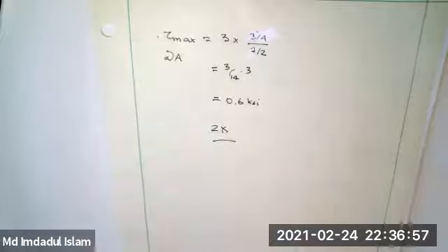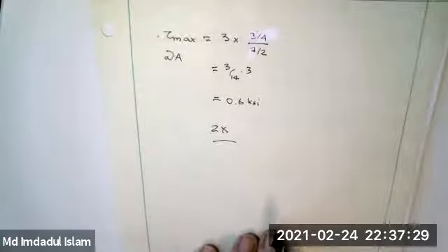So what I'm trying to tell you is the books give a lot of attention to the shear stress due to the shear force. Okay? There's quite a bit written in books about it. And it's all correct, at least as far as I can tell. The thing is that those stresses, first of all, they're at a different location. I've seen practicing engineers occasionally try to add the two. That's wrong. One's at the center of the shaft and the other one's the outside of the shaft, okay? And typically it's smaller. Even in this circumstance, it's a factor of 2. If somebody asks you for the maximum shear, let's go get the bending stress and divide by 2. Are there any questions on that?